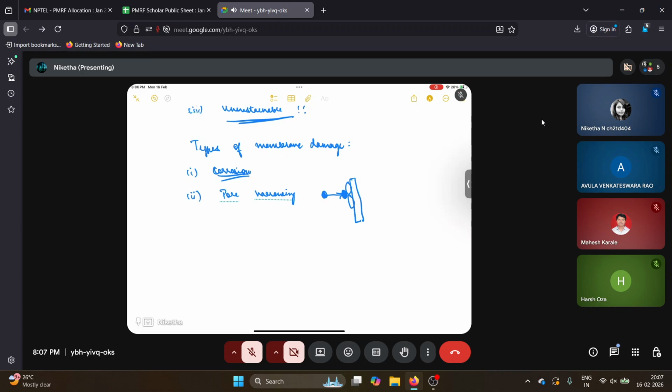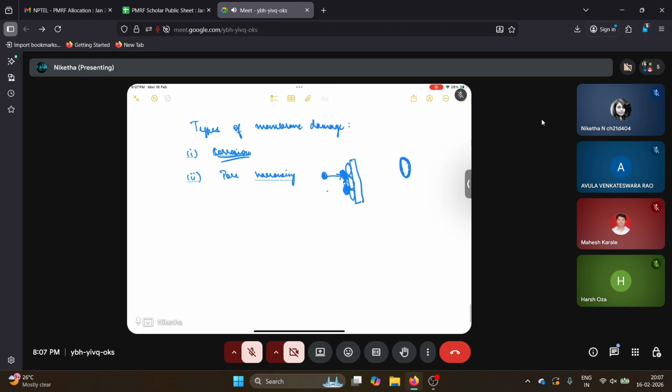And eventually, if we have a feed which contains some salts, then over this pollutant there will be some salt layer also. So the salt layer may also get deposited over time, and that will reduce the size of the pore. Now, salt can also directly sit on the pores, and it can reduce its effective area. So these two can happen. So pore narrowing is that.